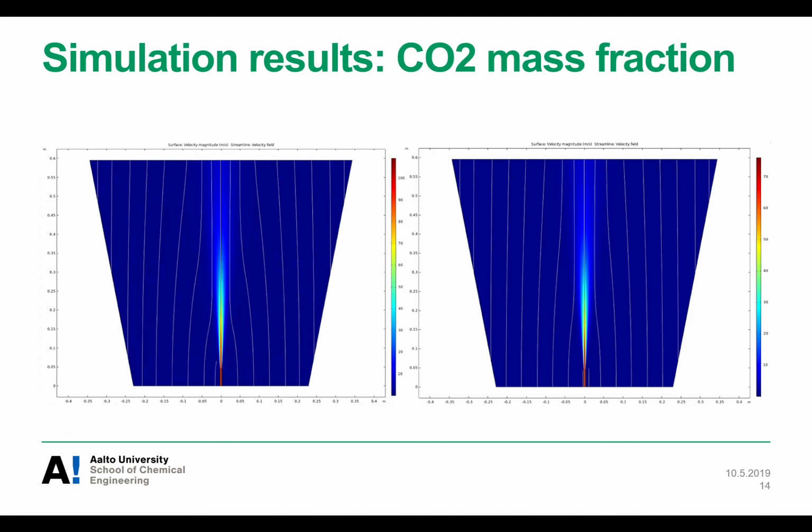Also, one thing really worth noting is that the flame is fixed to the exit of the pipe, which means that there is no lift off, and around that area there is more concentration of the exiting feedstock. The flame or the jet is fixed to a certain position, which is more or less seen also when you light a candle, because it has the same effect. So yes, with more velocity, the turbulence is higher.